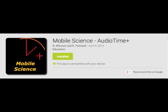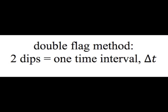The cell phone app Mobile Science Audio Time Plus sends out a signal through the headset port, through the resistors, and then looks at the return signal. If the resistance changes, then the amplitude of the return signal has also changed. And it's this change that's used for timing the photogates.